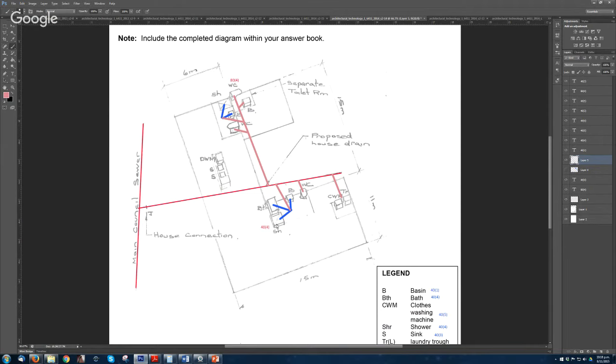And what, do you need a floor waste gully in each room, and not just one? Well, I think you do that to minimize the number of pipes going to that drain, and usually you put it in every room where there's bathroom stuff.